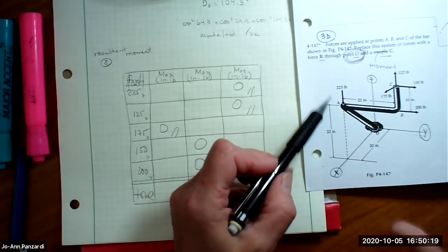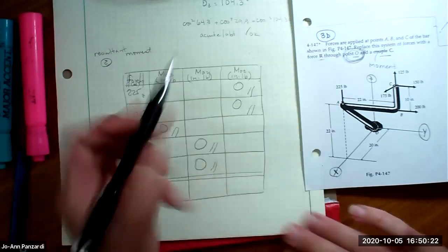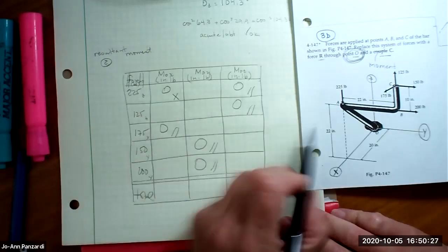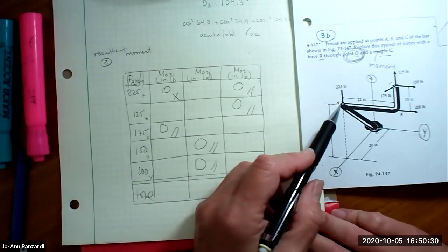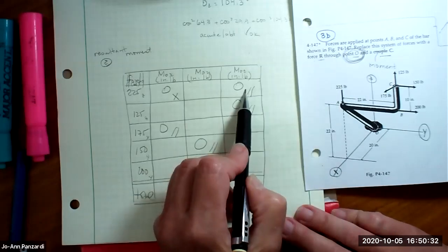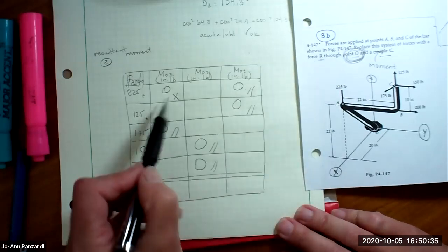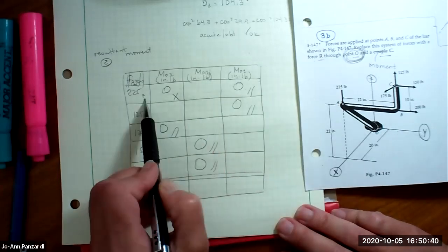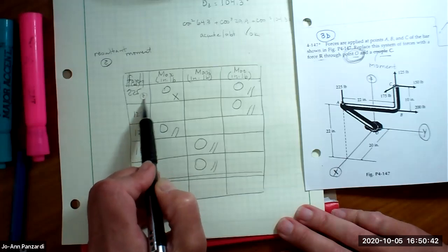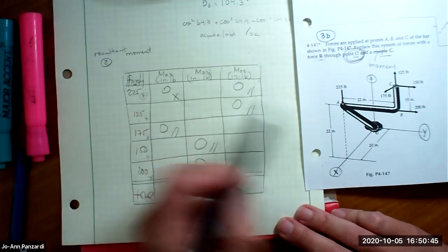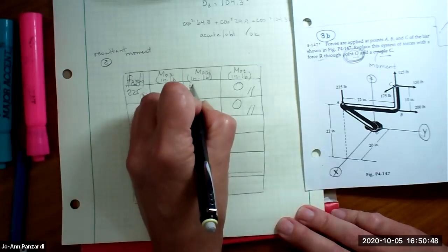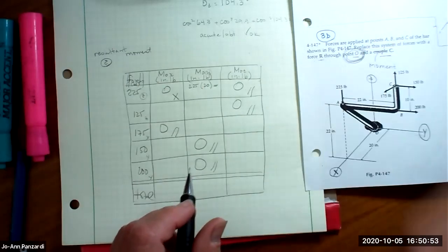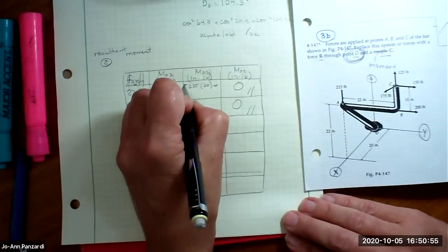Okay, are there any intersecting? Let's look at the 225. The 225 intersects the x-axis, so no moment there. So let's just stick with 225. It doesn't create a moment about the z because it's parallel. It doesn't create a moment about the x because it intersects, but it does create a moment about the y. So we're trying to find the moment about the y, and the force is in the z, so the distance is going to be in the x. The distance is 20. So 225 times 20. And let's see, fingers go in the direction of force, palm goes towards y-axis, I got a positive.